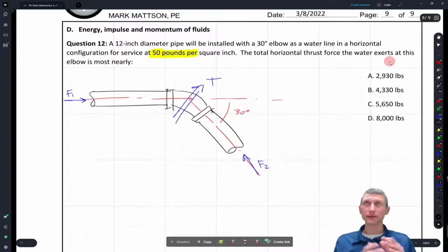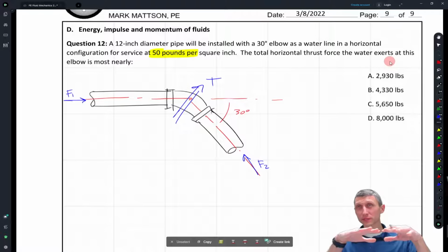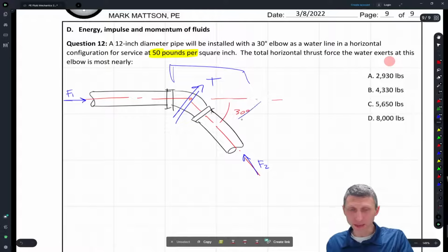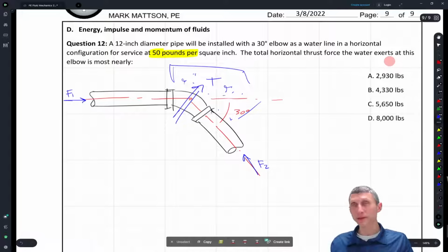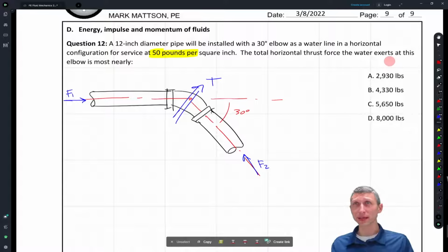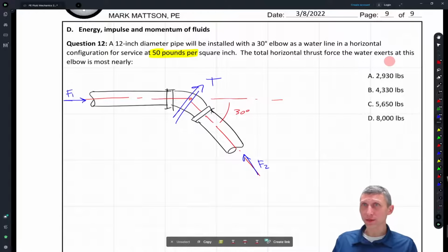Because typically in a piping system, the soil or the stone bedding material that you put the pipe on would take the vertical loads. You'd have some sort of a concrete thrust block out here to take this thrust force and make sure that you can distribute that load to the soil appropriately, so that it doesn't blow out your pipe. Okay, so that's what you would do in a typical civil application. So I figured let's use that for this. So what's that thrust going to be?